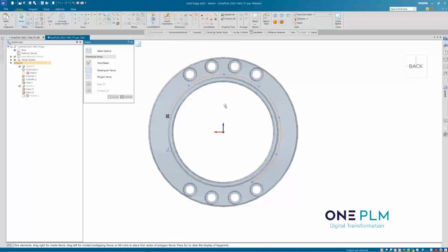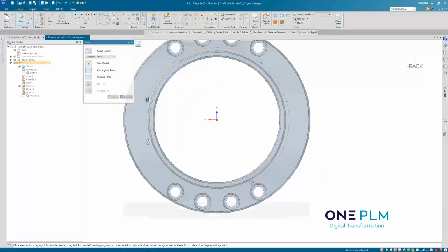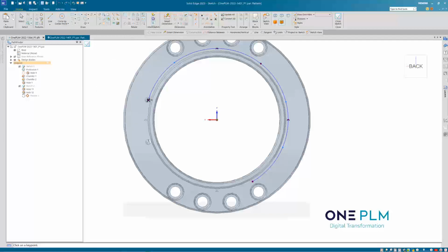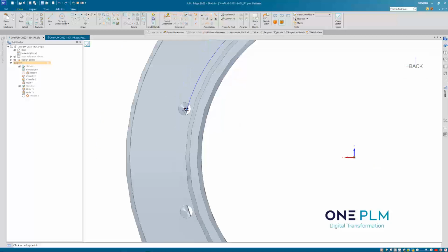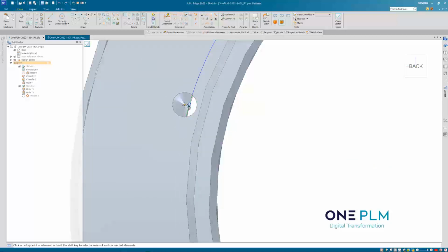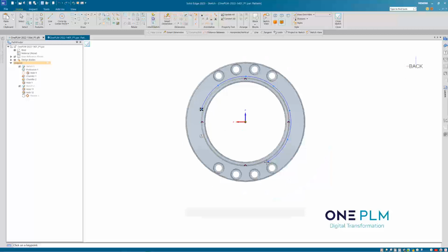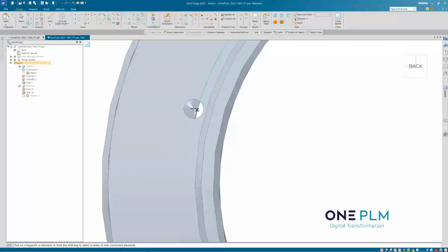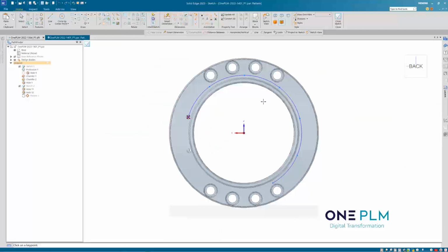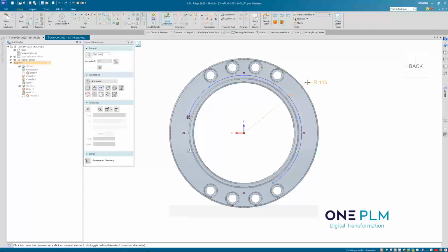Go back into your sketch. Make sure that everything is okay on there. It might be that there's some kind of relationship on there that is causing an issue. So we can go and delete and go and recreate the relationship to the appropriate item that we need to on there. So I think there's a relationship at this end as well that's causing the issue. So that's looking okay. Let's just leave it like that.